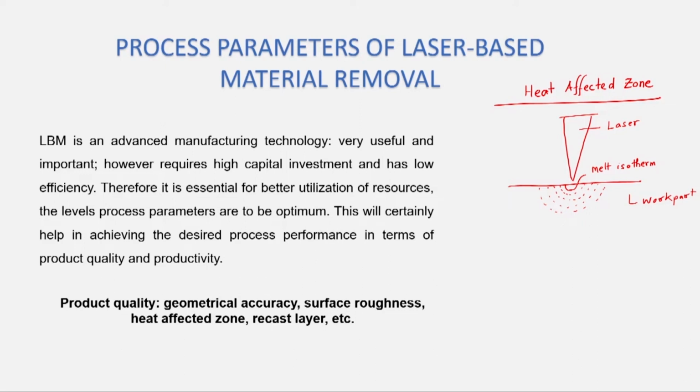During the application of laser on the surface, we have the temperature curves, which we call the isotherms. At the melting point, a certain volume is melted or removed, and afterwards it is removed using the inert gas. Based on this we can find the width of the laser cut, which is called the kerf.